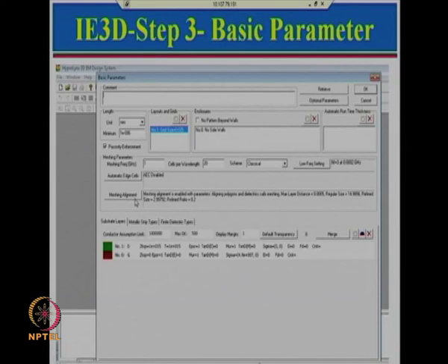Then this is mesh alignment, these are the comments related to the mesh alignments, and the next part is the substrate related specifications. The first one is substrate layer. Now if you see here, by default 2 layers are given. So the lower one is the ground layer. If you see here, it is written z top equals 0, epsilon r equals 1. So this one is the ground layer. Now let me show the interface first.